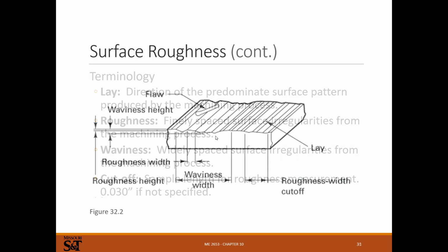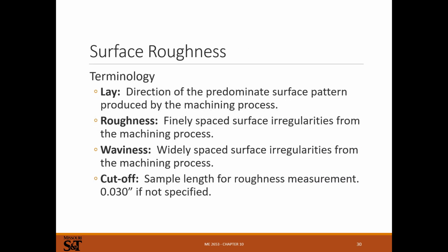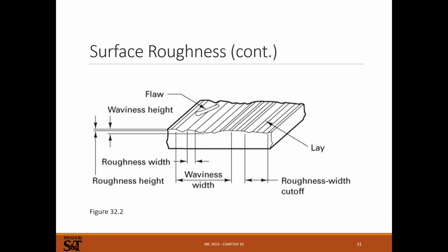Surface roughness. There's the dimensions that you measure, but there's also the surface finish too, and it's kind of hard to distinguish between these things. But you might have something that has a very accurate dimension that you'd measure, but the surface is very rough, and so you're really only measuring the peaks here. You're not actually measuring down in the valleys.